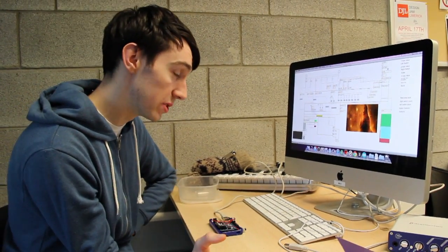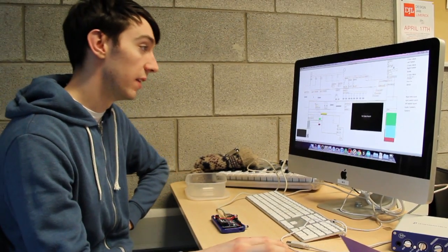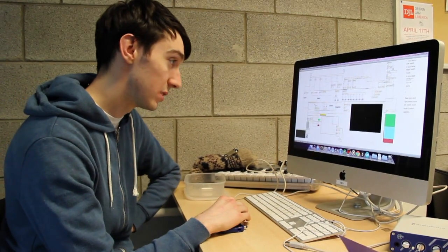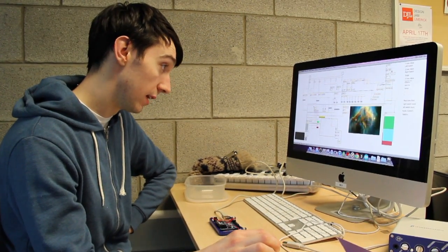For the Csound, there's two instruments. One is a random noise generator, and the volume of that is controlled by the Z-axis. So it kind of acts like a shaker. The harder you shake it, it's like an egg shaker on stage. And then the second instrument is an FM synth. And then I have X, Y, and Z axis, and I have an octave shift as well, controlled by one of the switches. And the carrier frequency is controlled by the X axis, and the modulator frequency is controlled by the Y axis. And then as well, I have one of the digital switches turn on a simple tape delay, which works kind of cool as well.